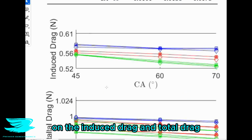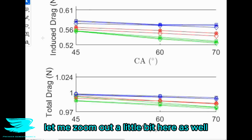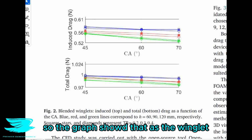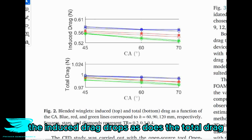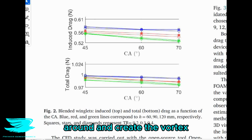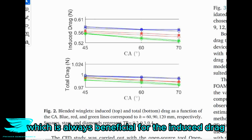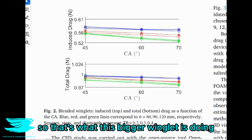Now in figure 2, we also see the effects of the winglet cant angle and height of the winglet on the induced drag and total drag, and this is cool. So the graphs show, let me zoom out a little bit here as well, that as the winglet increases in height, the winglet becomes taller, in other words, the induced drag drops, as does the total drag. And that makes sense because the taller the winglet is, the harder it is for the air to bleed around and create the vortex. So in other words, the greater the disconnect between the lower and upper surfaces, which is always beneficial for the induced drag, that's what happens. So that's what this bigger winglet is doing.